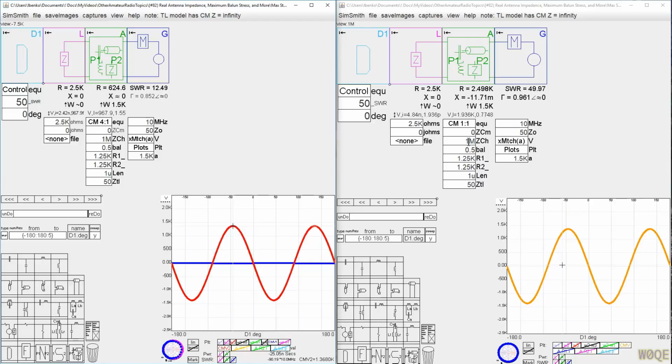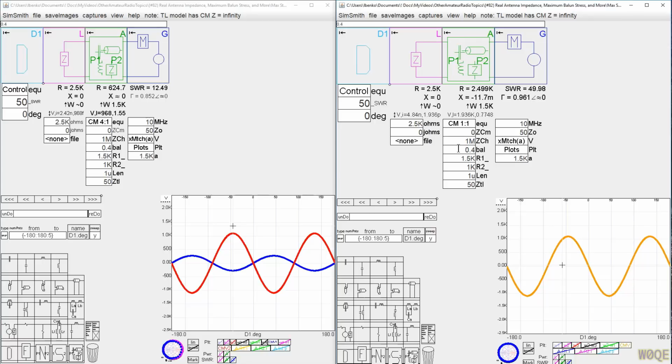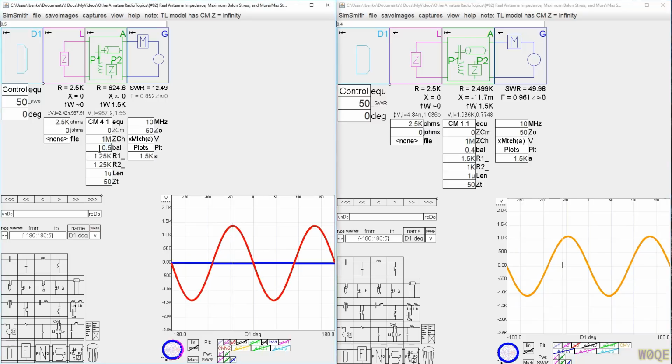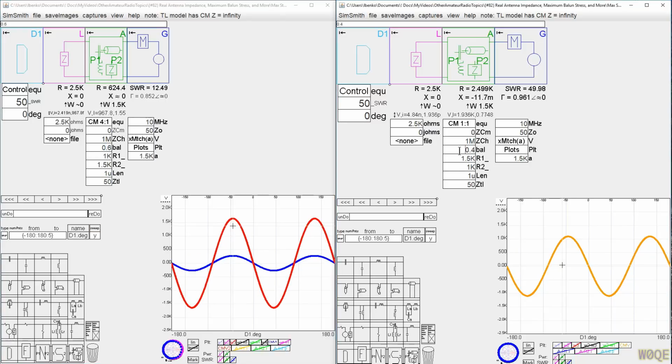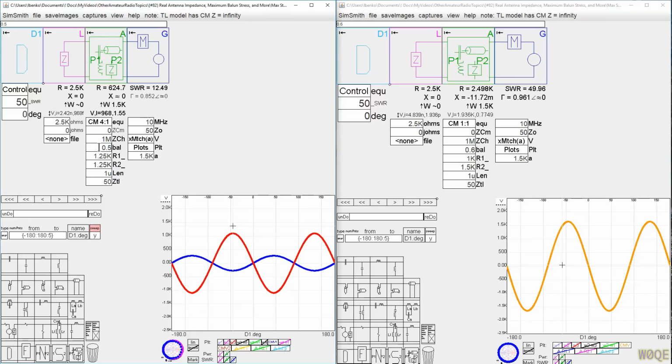And let's look at what happens in terms of stresses as we change the imbalance in the load. If we drop this to a 0.4 balance versus 0.5, again, the worst case choke here sees the same stresses. If we go to 0.6, it sees more than it did at 0.5. If you had a circuit where you knew your antenna was imbalanced in a certain direction, you could swap the two leads to the Balun and turn that into that, if you wish to.